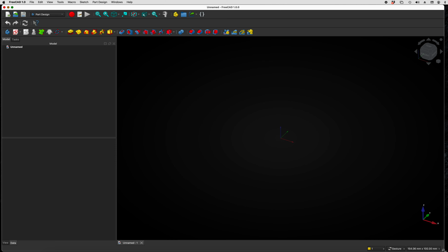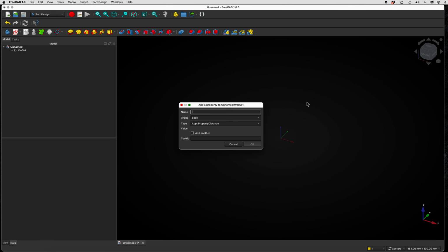Well, since we've already done the technical drawing offline, let's just go ahead and set all our varset parameters right now so we can add them in as we're building the model. So in FreeCAD 1.0, here we have the varset parameters. We click on it once and we can now name it. As I said earlier, we've got body diameter. Has to be one word. Help if I actually spelled it correctly, wouldn't it? Body diameter. Okay?